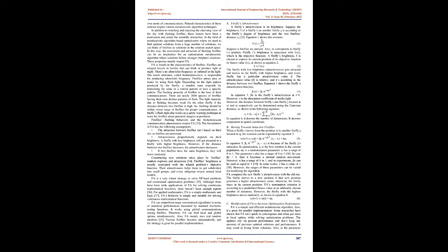An accelerated variant of FA, named Fast Firefly Algorithm, FFA, has shown strong optimization performance by solving some benchmark functions. FFA has been superior to the original FA considering convergence rate towards the global solution following a similar precision. In the application of controlling a BLDC electric motor, FFA showed its optimization efficiency by optimizing the motor's proportional integral regulator parameters using the IAE, ISTE, ITAE, and ISE performance criteria 30. In this optimization, FFA has been competitive against other metaheuristic algorithms like FA, PSO, GA, and ABC.